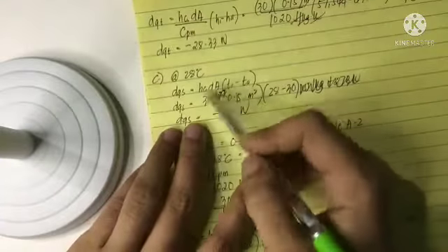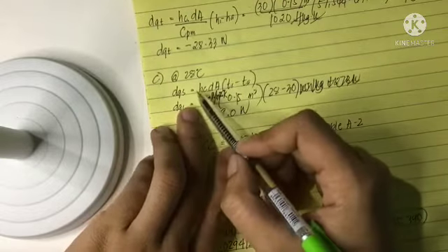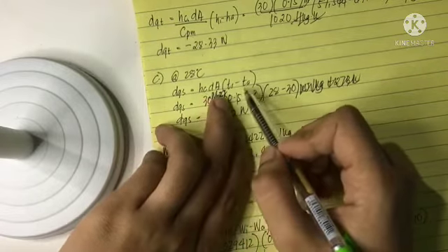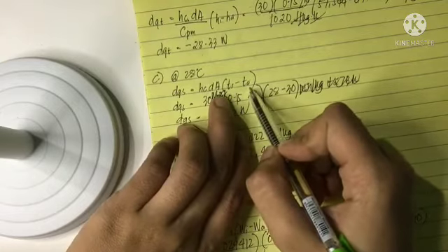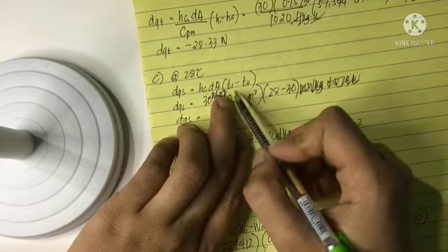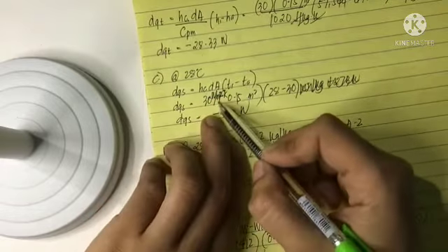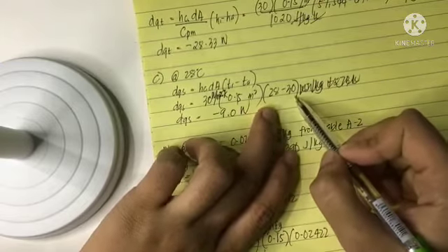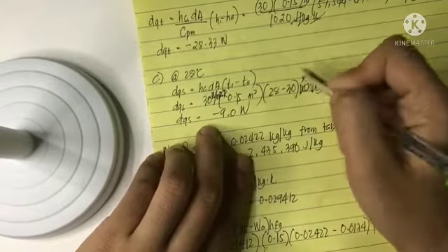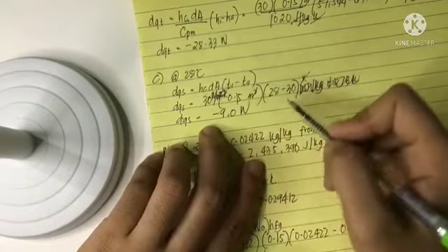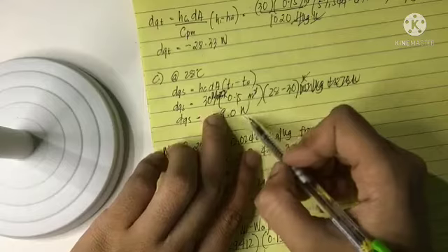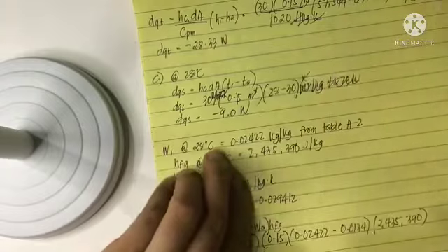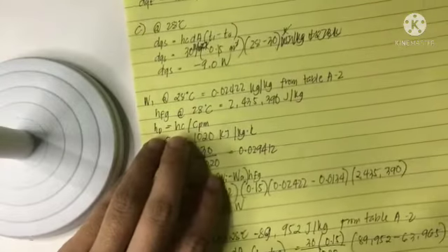So at 28 degrees Celsius, solving for our sensible heat equals your convection coefficient times your area times the difference of your temperature of air and your wetted surface temperature. So 30 watts per meter squared Kelvin times 0.15 meter squared times 28 minus 30. So Kelvin cancels out your meter squared. So what unit left here is watts. We have the final answer is negative 9.0 watts for our sensible heat.